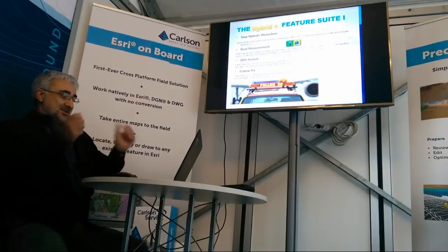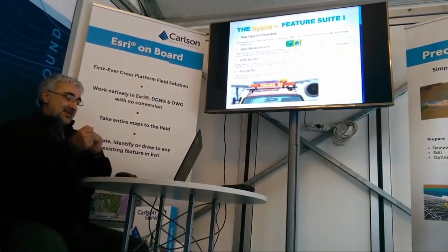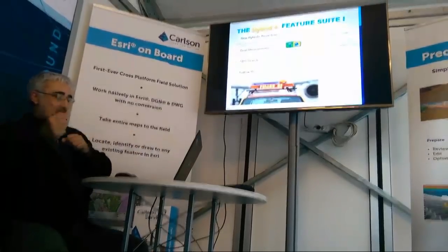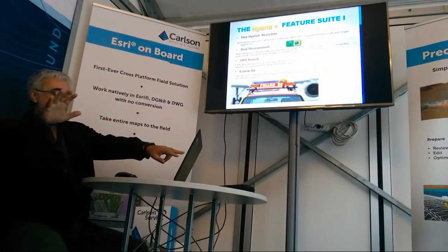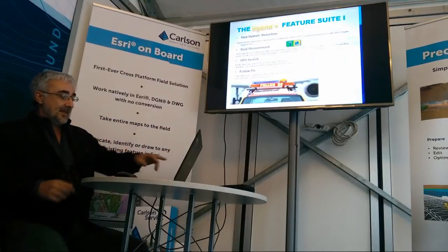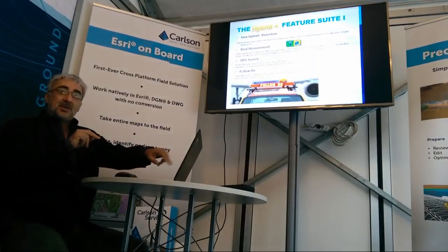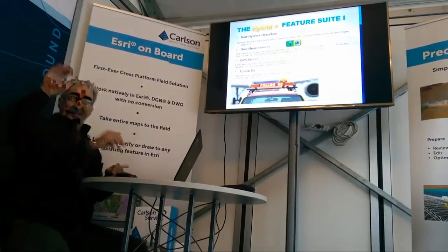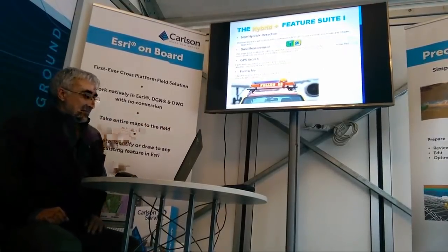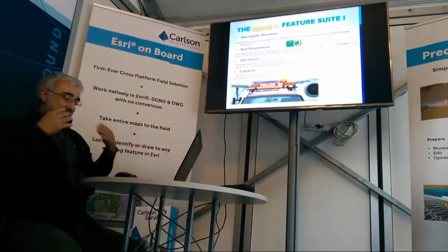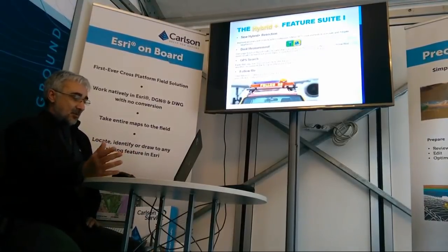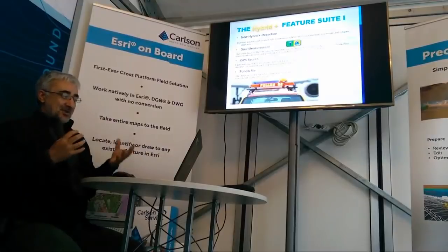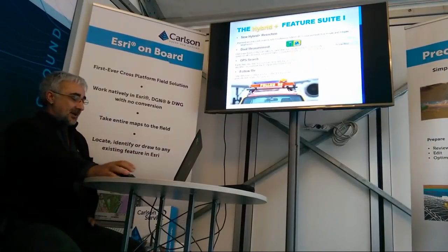And then you can change your main instrument anytime, in any place, in store points in the menu. So maybe there is a hidden area, you cannot use the total station because there's no visibility. Then you quickly switch to GPS and continue working in store points. So it's easy, it's quick, it's very reliable because one instrument is cross-checking the other, right?